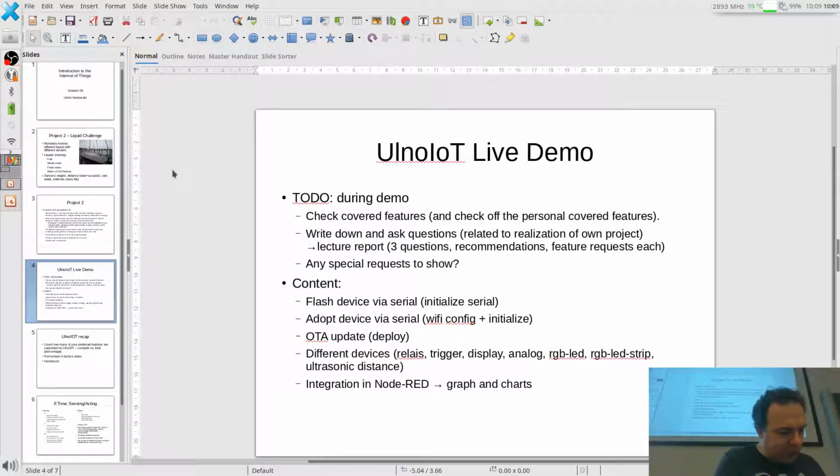No, to analog. So some of you have used the analog sensors already. Very important that you wire it to the A0 port on here, yeah? There's only one analog port on these devices. So that needs to be A0. And where did I put this? Here. So A0 is on gray.